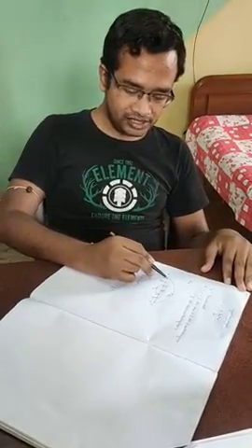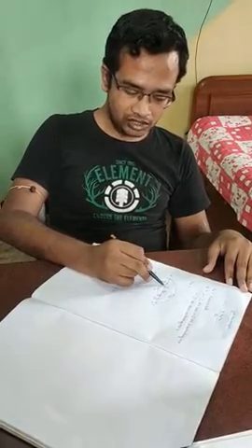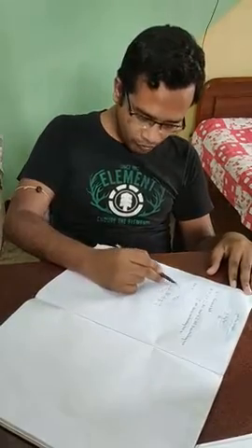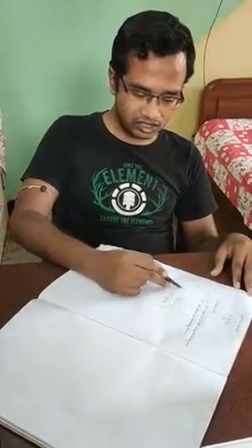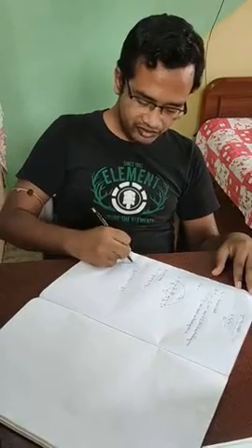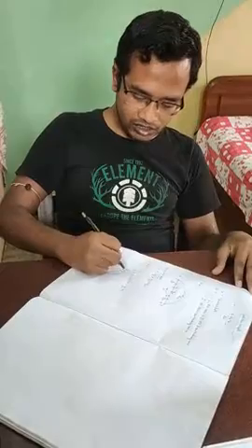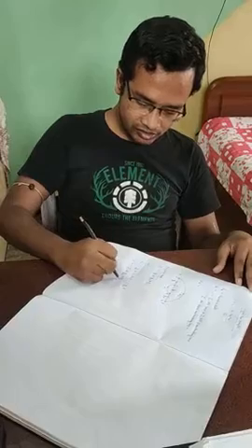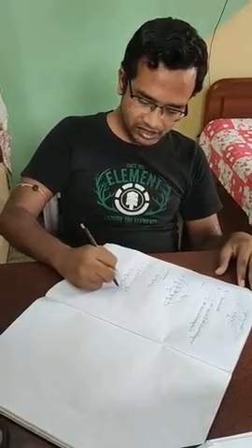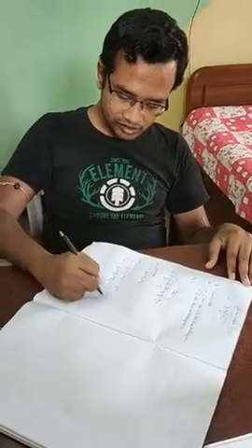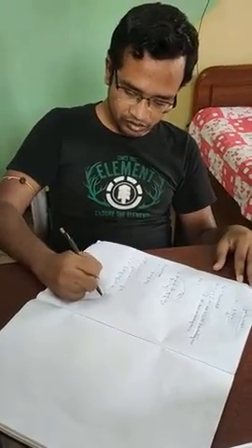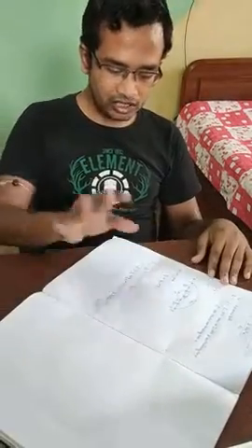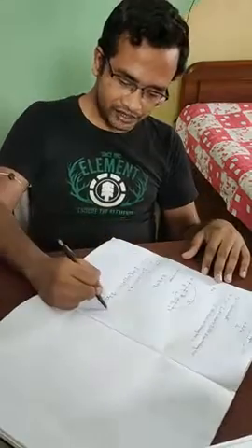And there is another loop here. Start from node 1, G1, then from node 2, G2, then from node 3, G3, then again return back to node 1 by minus H2. This one is a bigger loop. So there is another loop L2 equals G1 times G2 times G3 times minus H2, which is minus G1 G2 G3 H2. Now there are no other loops in this graph, so we have segregated our two loops.